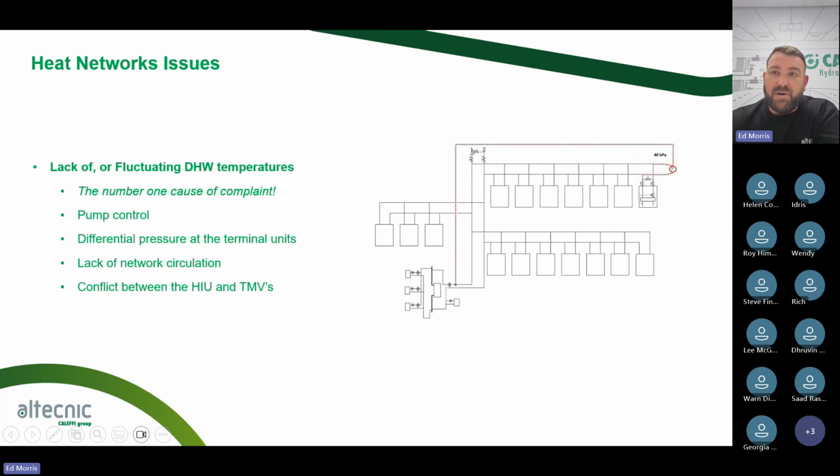Different pumps will work off different ways of sensing. So in this instance I would always get clarification from the pump manufacturer or the booster set supplier, whoever is doing the pumps, on where they would place it. But it has to be at the most remote part of the system to ensure we get the right amount of differential pressure or energy to go through the HIU. I hope that one's cleared up. In any case where there may be questions, always speak to the manufacturer and see how their equipment will work best.